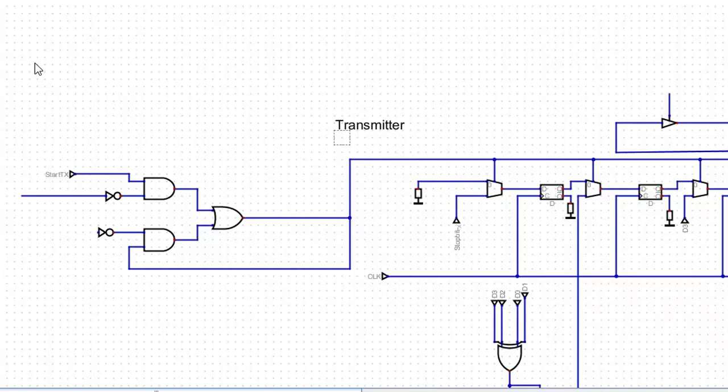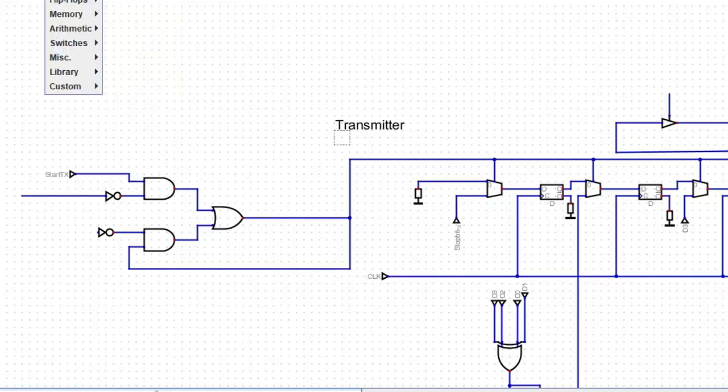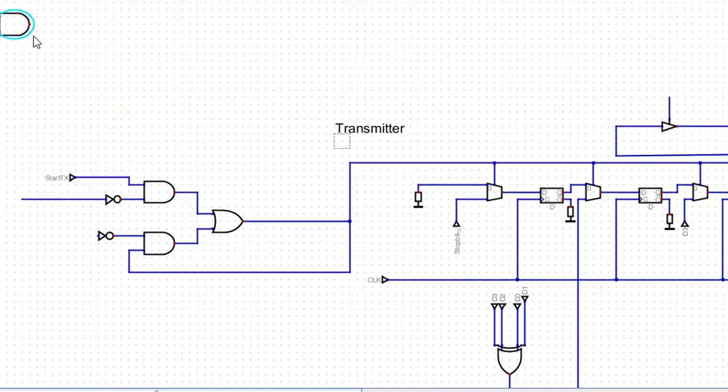Okay, Mr. George Coyote, also known as Praise. How do you check whether 6 has been reached? Try AND gates. Exactly. So please do that. It's under logic. How many bits do you need to check? 2 bits. Okay, which 2? I'm just going to write this down. Six is 110.